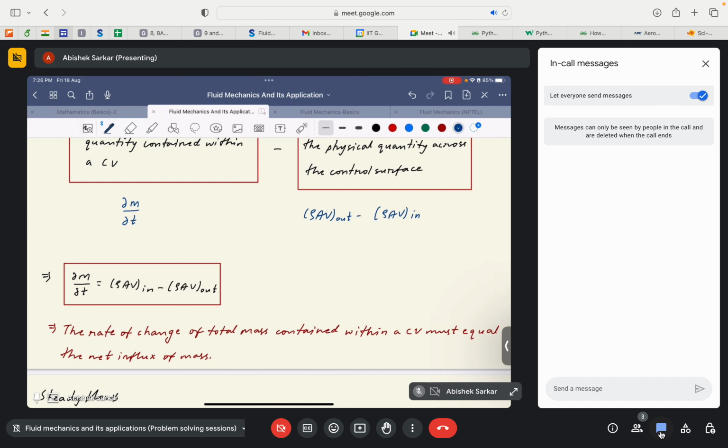Since the cause because of which the effects of the wall are felt is itself not there, that's why the velocity profile remains uniform. You will see how we are assuming that, and that in turn simplifies all our problems. It's a good thing that you have asked. Though energy losses usually come in, at least in fluid flow, because of the effects of viscosity. It can come in other cases also, but we basically deal with viscous losses only. So that's the thing. Okay, thank you.